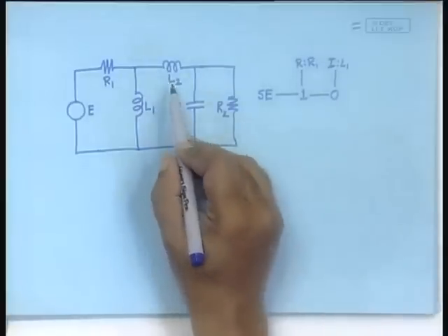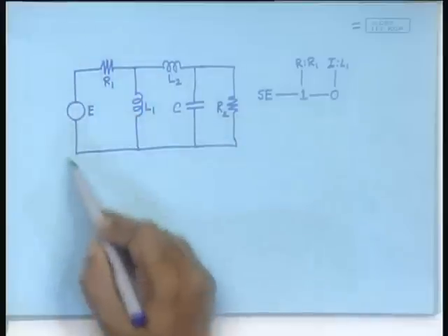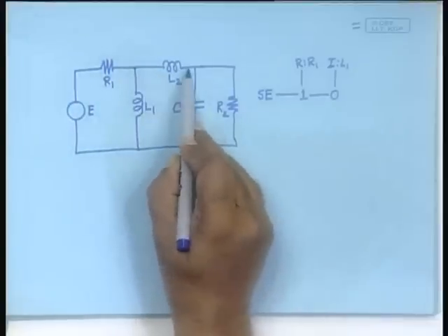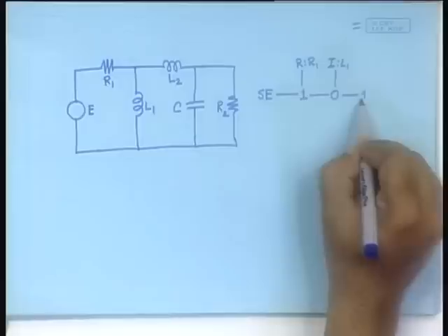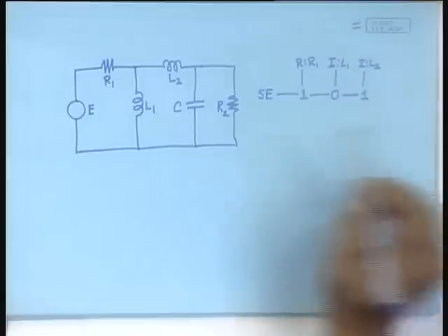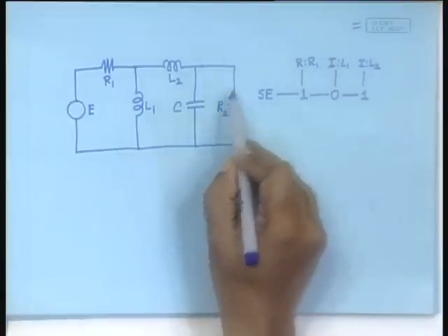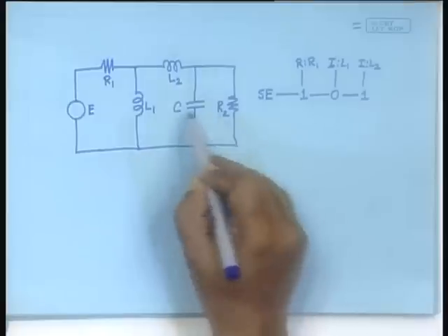Now, after this stage, it is in series, whatever this combination is, that shares the same flow with L2. So, it will be a one junction connected to I L2, and finally, here these two share the same effort, they have the same voltage.